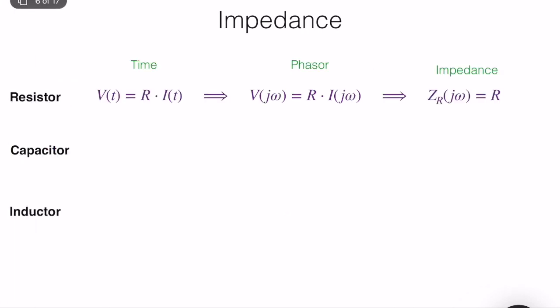Good. So let's look at resistors. In the time domain we have this simple relationship. We have this phasor expression. We already know that. And the impedance of a resistor is simply its resistance. Nothing changed. Now let's look at the capacitor, and remember the capacitor's time domain equation: C times v dot is equal to i. We can transform v dot, the derivative, using the concept of phasors.